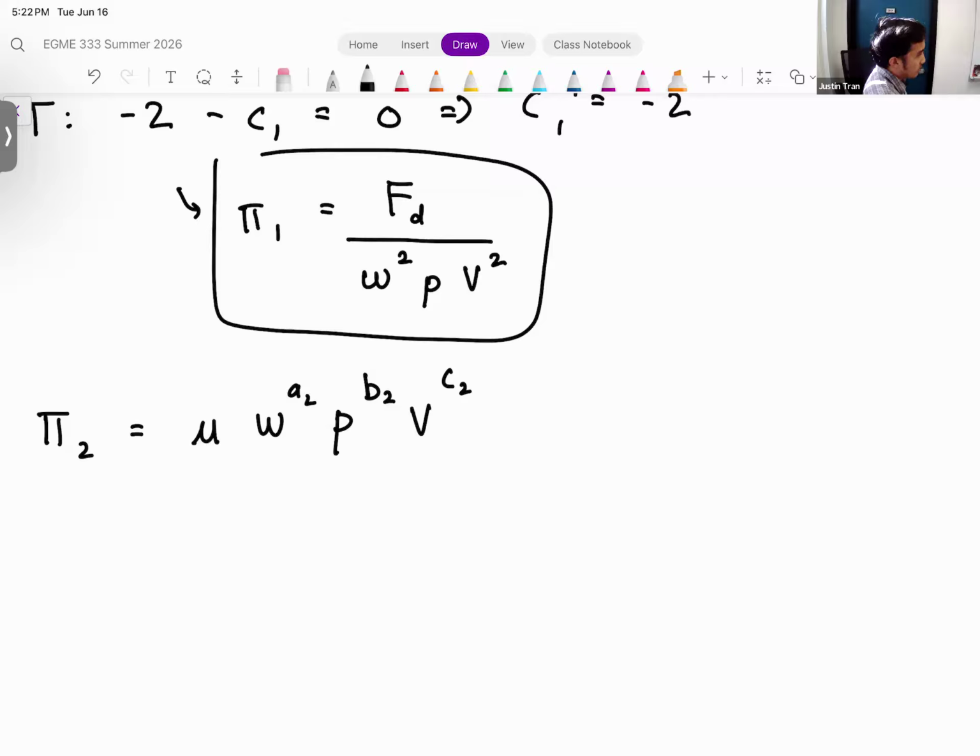So we can go through this again, but if you compare this to our pipe flow example, we did a pi term that was identical to this, right? For our pipe flow, we also had a pi term that involved viscosity. The only difference was that instead of the width, we multiplied by diameter, but dimensionally they're the same. So width and diameter both have a length dimension. And so just in the interest of time, I'm going to go ahead and refer back to the previous example.